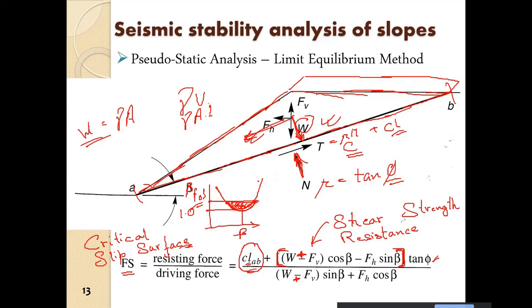So it is likely that the entire wedge or the entire slip surfaces fail. There may be a progressive kind of failure. It may start with the steepest one. So if this is the slope, it may start with the steepest one and then it will retrogress in this manner, and then from here it will fail up to here.